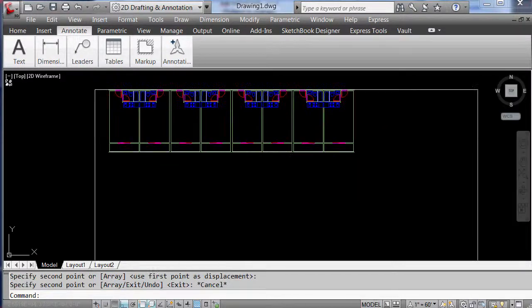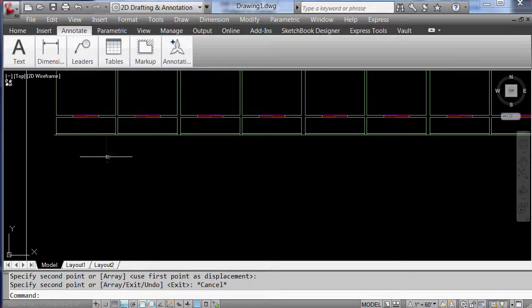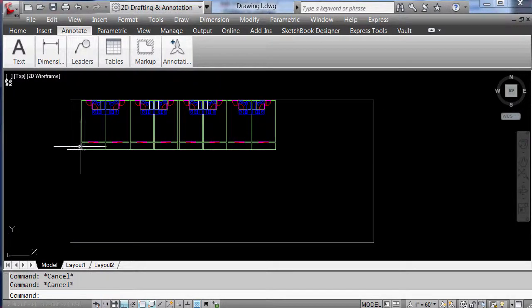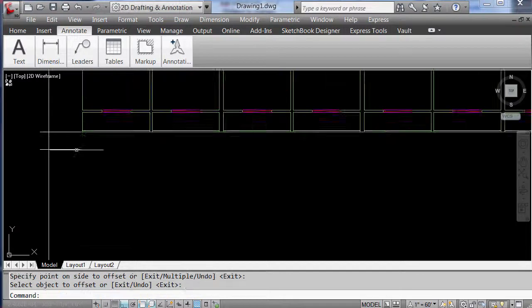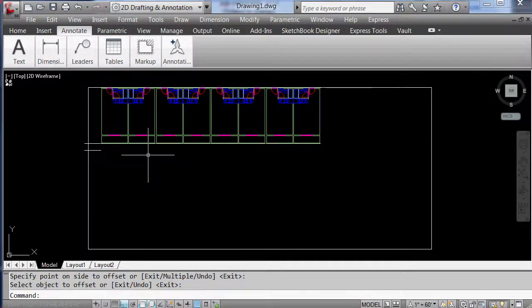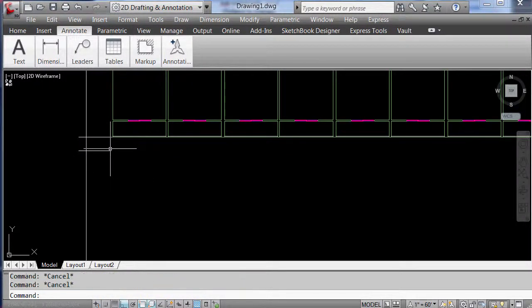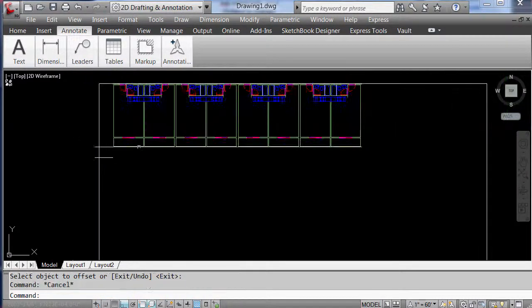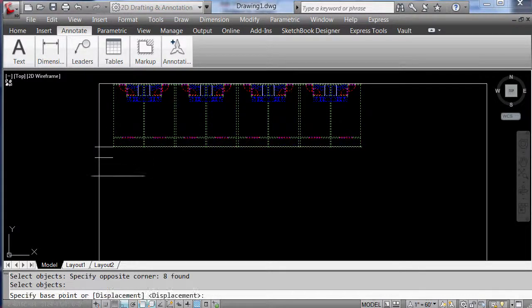And then now all I need to do is select the width of the hallway, and if I'm not mistaken, the hallways are usually 42 inches. So I'm going to offset this 42, and that's kind of a narrow hallway. Let's say 5 feet. That's 60 inches. Better.